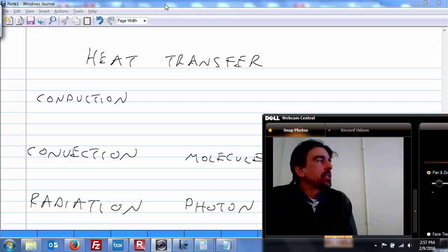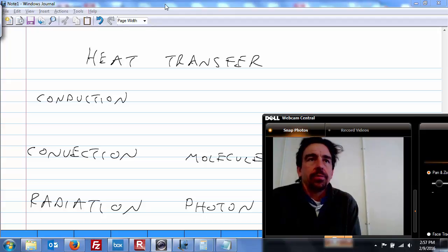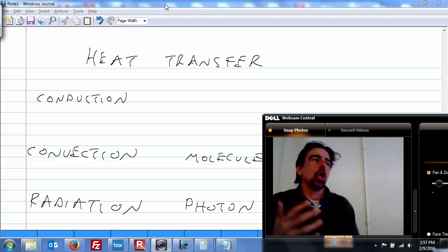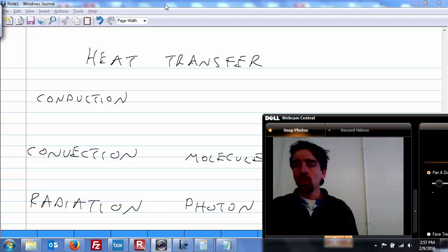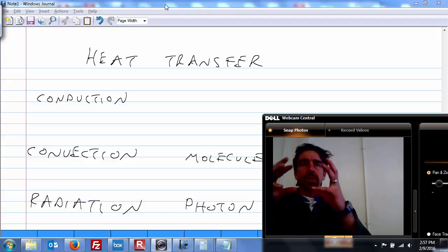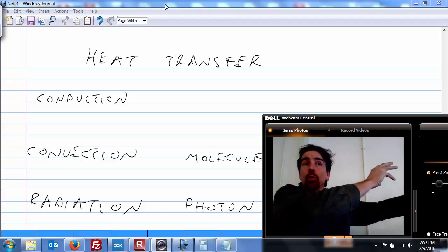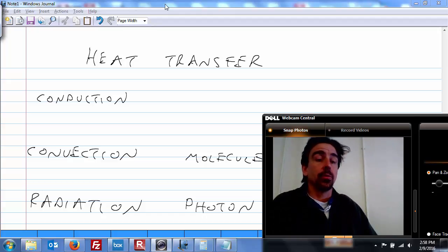So heat itself and temperature can really be thought of as just the average velocity of the molecules in a system. So the faster they're moving, the faster they're vibrating, the hotter something is. Fundamentally, that's all thermal energy is. It's just vibration at the atomic scale. So all you're doing in convection is just moving one set of quickly vibrating hot molecules over somewhere where there's a bunch of slow moving molecules somewhere else.